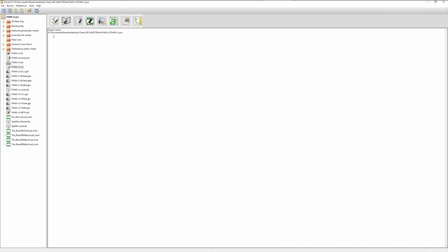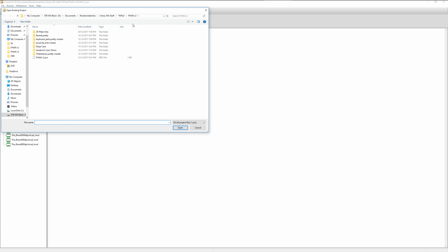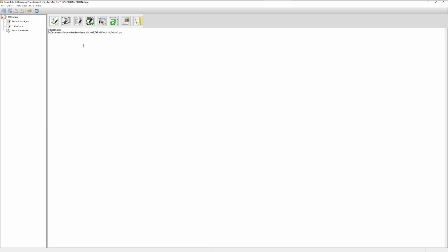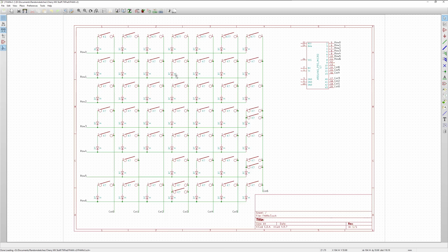The schematic is relatively simple. You don't have to do terribly much. It doesn't require a huge amount of thought for a very basic matrix. If I was to do LEDs, I would have to have additional components here, because I would now start to put resistors and the LEDs in parallel, and then they all have to go to a transistor and another resistor to the Pro Micro, so that there will be no overcurrent issues. And I didn't want to make it more complicated. I didn't want to make it harder to run traces, because running traces was really challenging for me when I first started, still is, and we'll discover how bad it is soon enough.